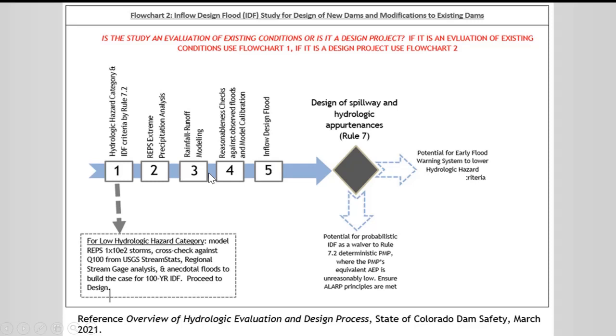We want to have reasonable inflow design floods, just like we want to have reasonable floods in the hydrologic risk analysis. So once we've made the case against the observed flood record that the model is giving reasonable results, we can use the inflow design flood that comes out of the model. Okay, so that then we carry into your decision